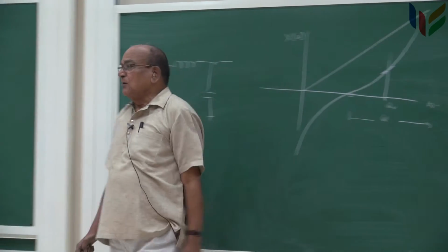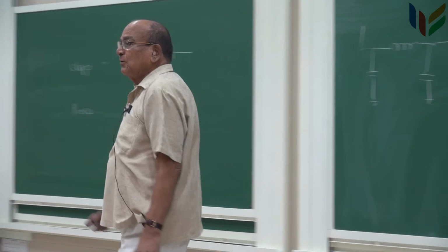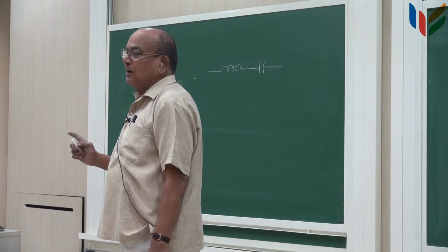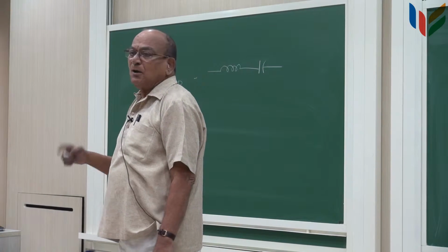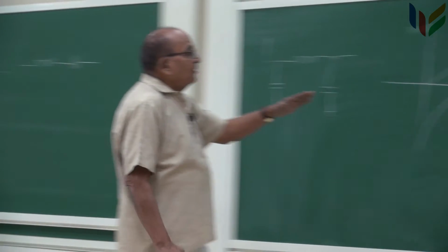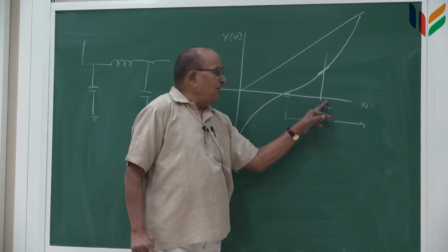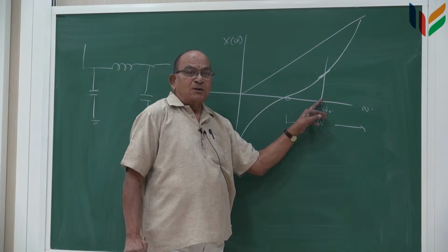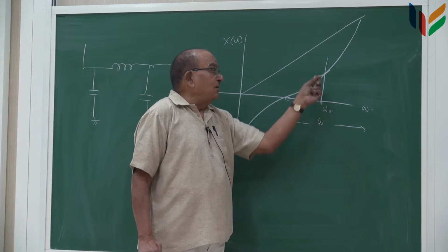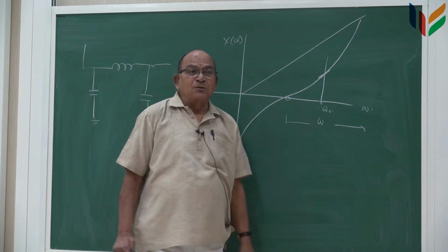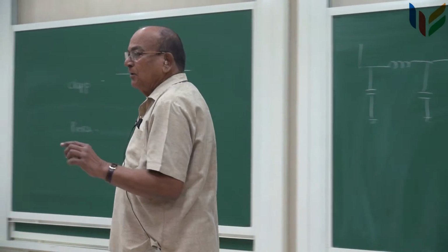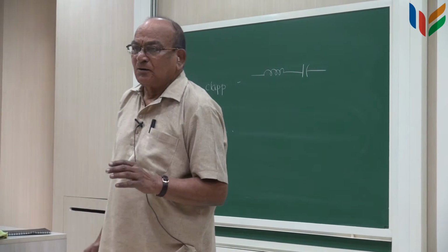As a result of that, we can show, I will not go into that, but we can show that the frequency stability of this oscillator is much better than the corresponding Colpitts oscillator. So, whenever we have a variation around the oscillation frequency, for a small change in omega naught, the X changes by a much larger value in X(omega), then you will have a much higher frequency stability.